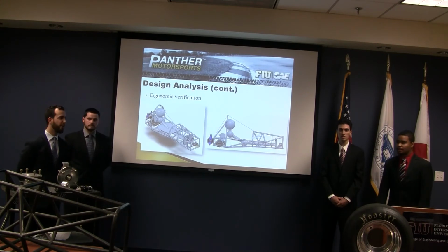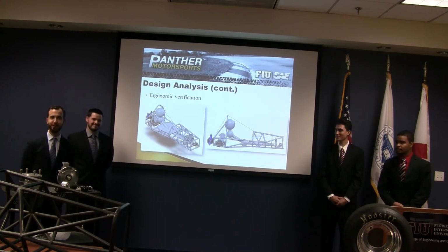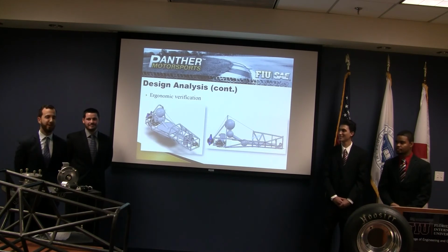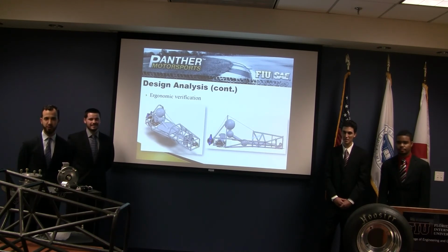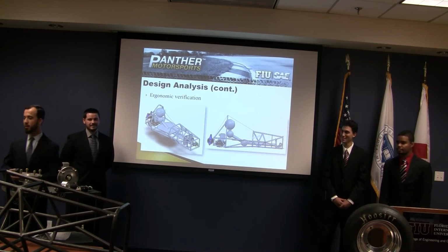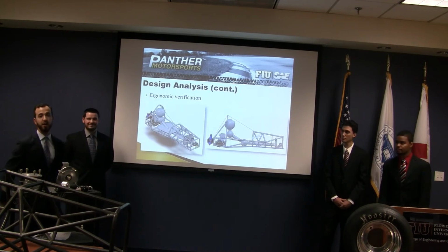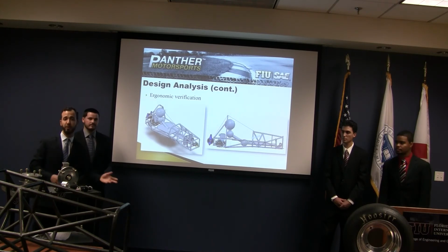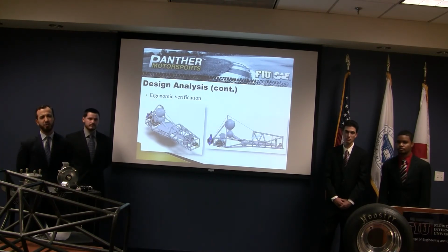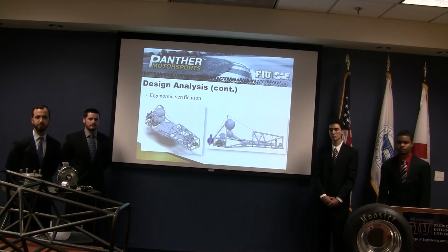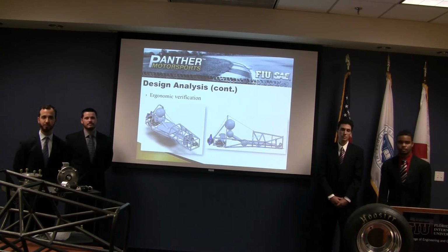For instance, for prototype 1, our suspension adjustability was from -8 degrees of camber to +8 degrees of camber. For those of you that are not educated, that is way too much. Our tire, after 1 degree of camber, is really useless. So in turn, it made our suspension mounts roll outward and cantilevered, which we got points taken off during the design competition. So we came back and assembled during the summer, and discussed what was good about the car, what was bad about the car, and those were all the engineering decisions we made towards prototype 2.